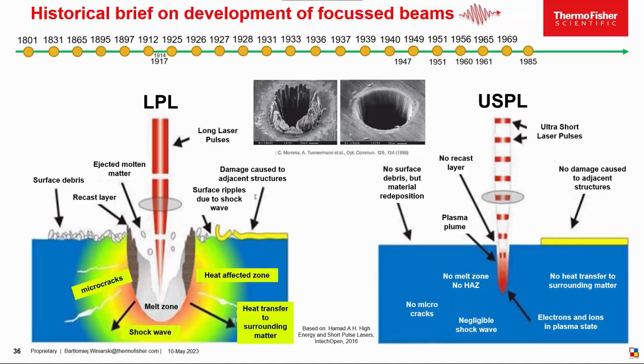This description is a large simplification, since the physics of photon interaction with metals, dielectrics, and insulators is different. As we can see, the laser ablation process is athermal, thus we are not inducing microstructural damage. Please see the micrographs above. Now, these features of USPL allow application of these lasers for fast and precise micromachining.